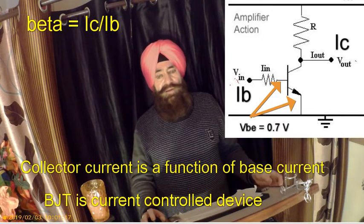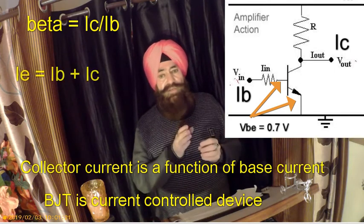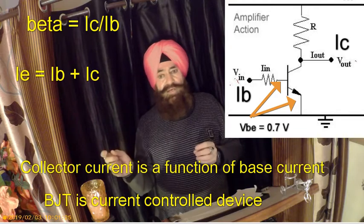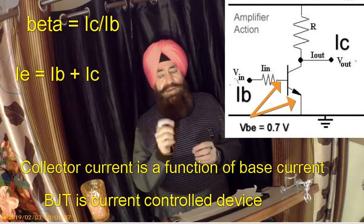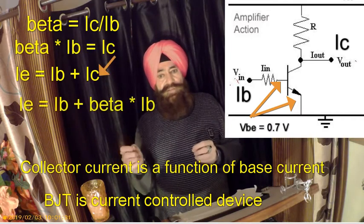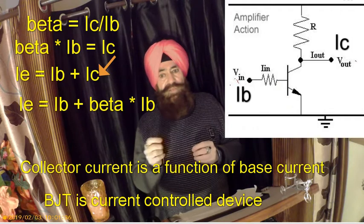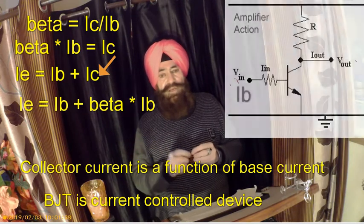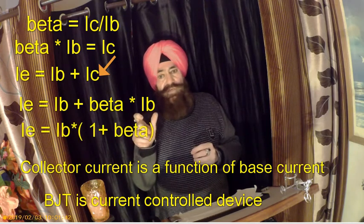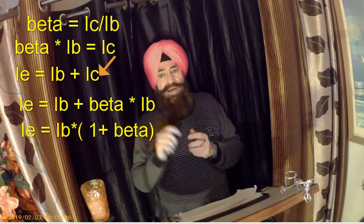Now there is another transistor equation: the emitter current equals the base current plus collector current, and the collector current is written as beta into IB. Substituting the value of IC, the equation becomes IE equals beta plus 1, within brackets, multiplied by IB.